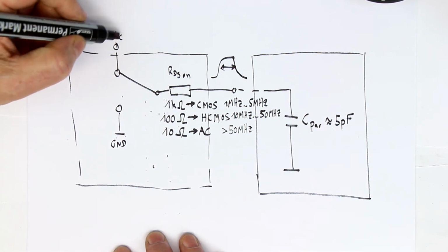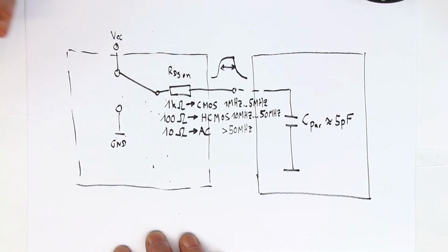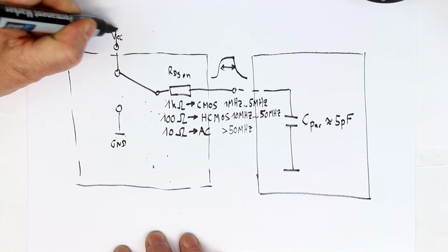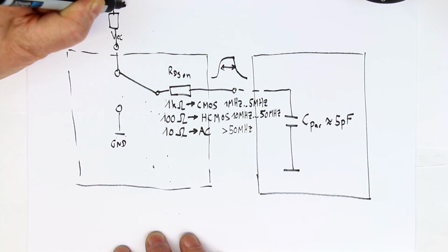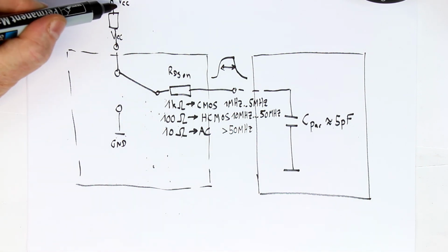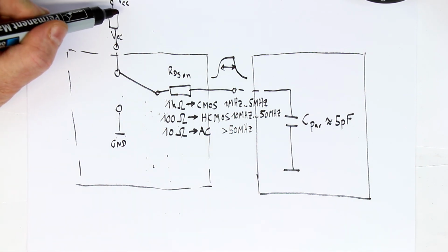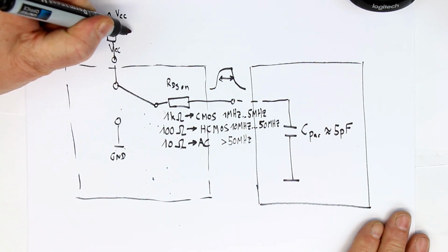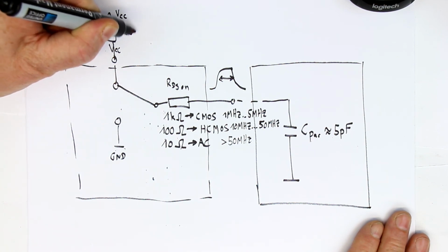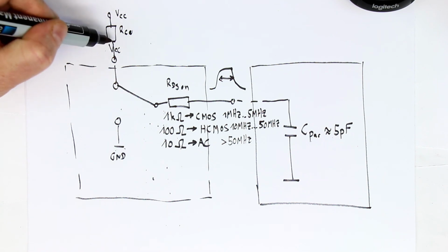And the first thing you will guess is that of course you have the copper resistance from your power supply, your regulated 5 volt or 3.3 volt or whatever, and that the copper resistance is the culprit here.